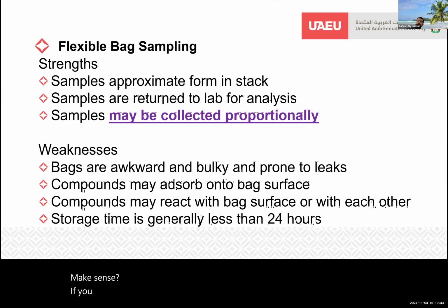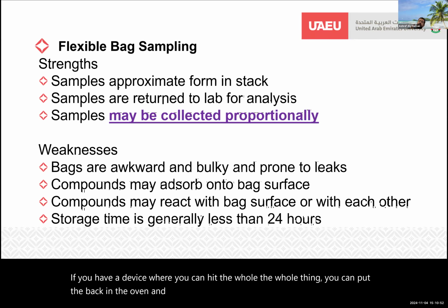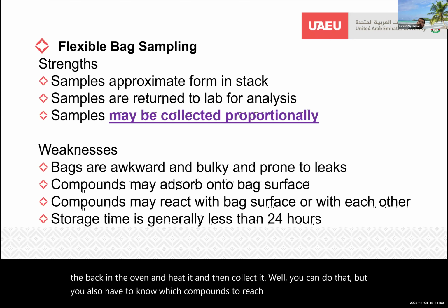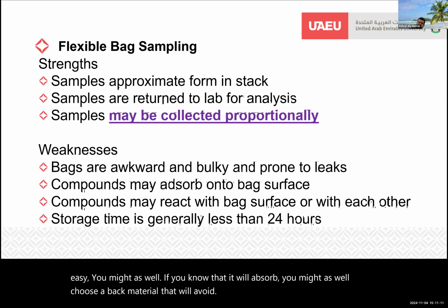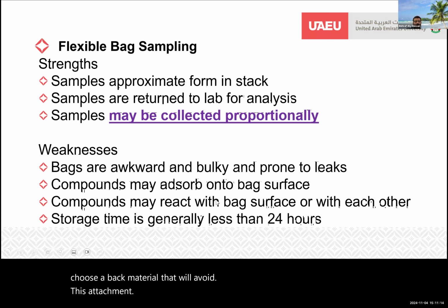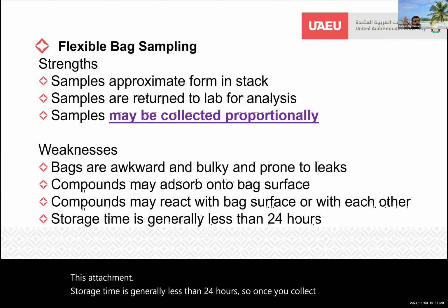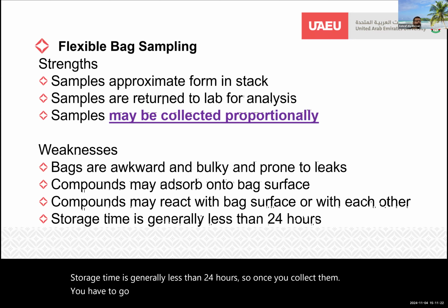If you have a device where you can heat the whole thing, you can put the bag in the oven and heat it and then collect it well. You can do that, but you also have to know which compounds to reach the required temperature. Not very easy. If you know that it will absorb, you might as well choose a bag material that will avoid this attachment. Storage time is generally less than 24 hours. So once you collect them, you have to go back and test them right away.